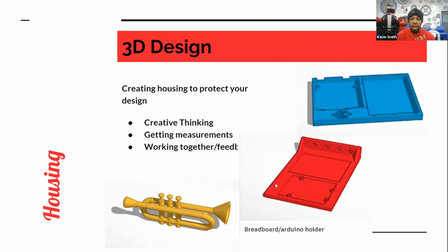So this is where most people may have been introduced to Tinkercad, with the 3D workspace where you can really 3D design a lot of different things. This is an example: to the right, in red and blue, are really basic housings that will house the breadboard in the larger square area, and the Arduino in the smaller square area. You'll notice that there are cylinders placed in very strategic points so that you could have screws to lock in the Arduinos and make sure that's a nice snug fit, if you like.